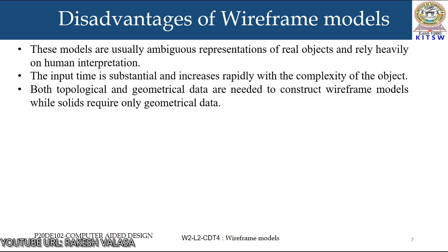Creation of a simple box as a wireframe and solid. The location of one corner, the length, width, and height are the required input for a solid, while in the former the coordinates of at least four corners of one face, the depth and edge connectivity are required in wireframe model for considering the box as a two and a half dimensional object.